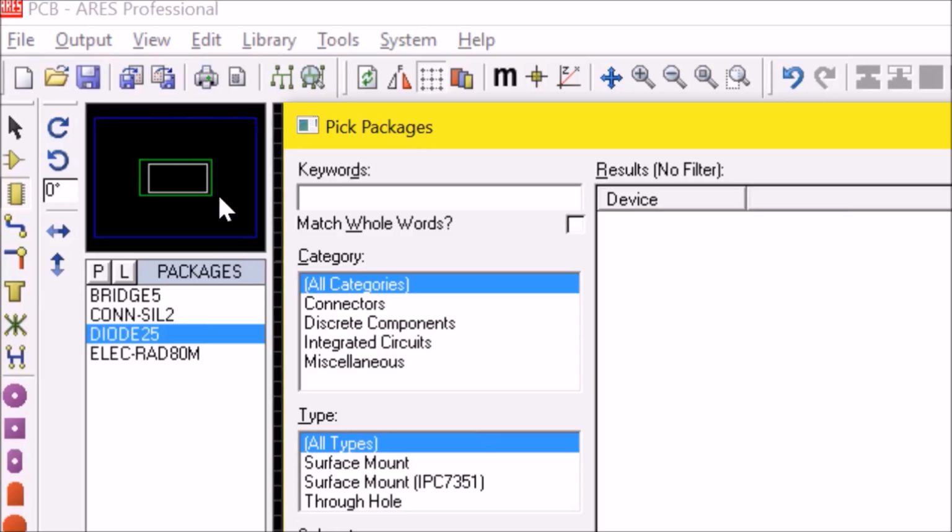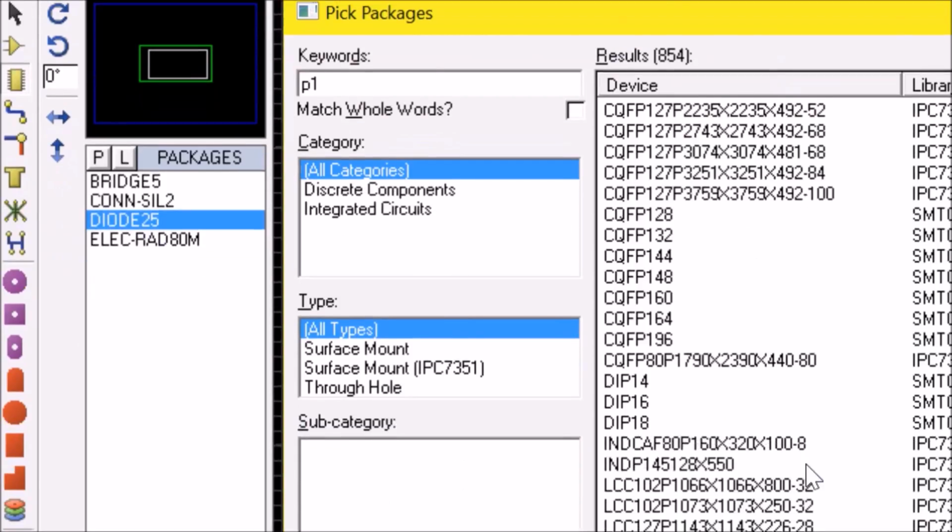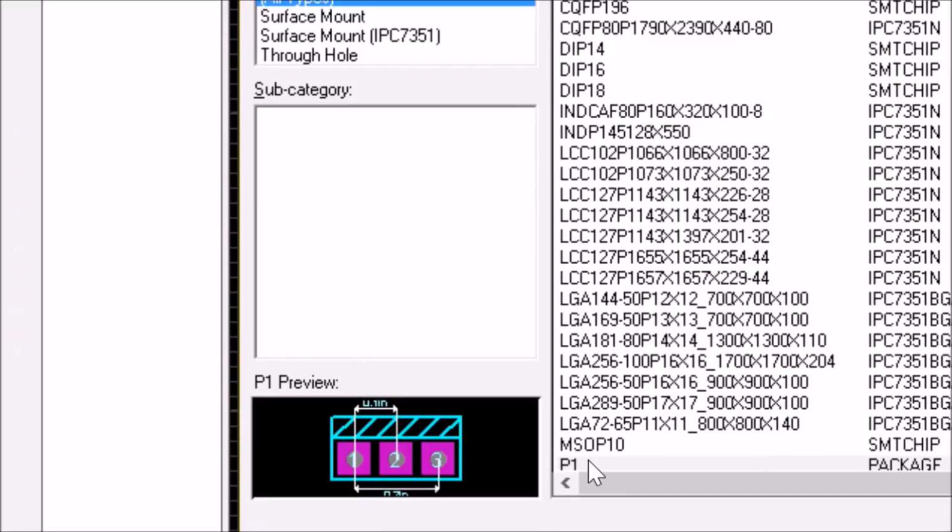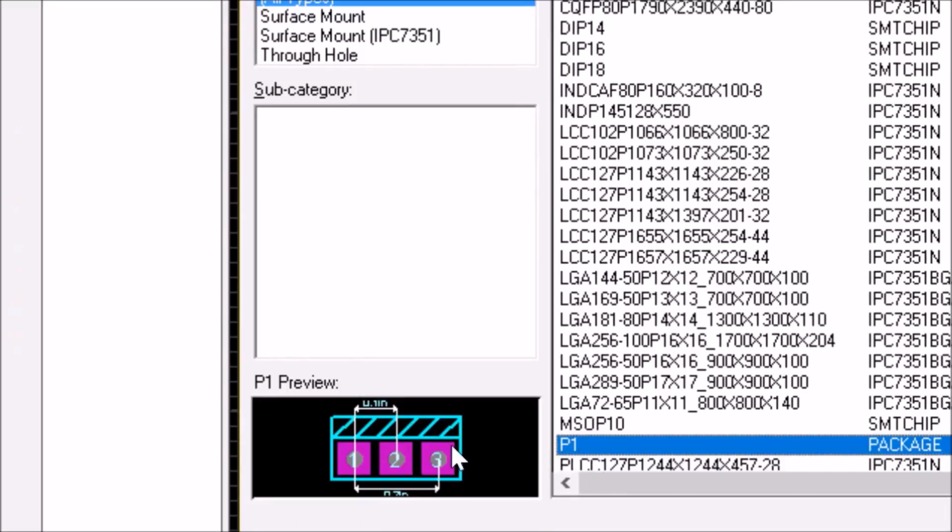Check it out, and you can see that what I have out there is a 5 volts regulator. That's my 7805. Yeah, I have 7805 there, and if I have 7809, 7812 or 7815 or 18 or 24, they are all just the same shape, and they have the same width in terms of the leg size. So go ahead and just type P1. Yeah, just type P1, and down here I'll just click on this. You can see my P1 here.